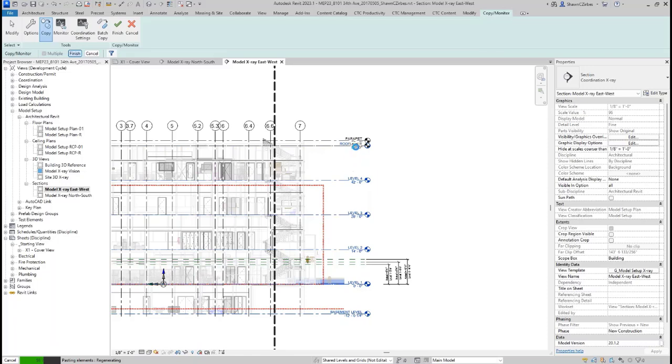The wheel will stop spinning for one, but my level R here is actually going to get renamed to roof level. So it should update that here in just a moment when it's all done. My level 1, which is capital L, lowercase evil, will become all caps as well, and it'll be called level 1. Because of how I name my views, by the way, it doesn't matter what the actual level name is because I use an abbreviation on my levels so that they always sort the same way, regardless of what naming convention the architecture team tries to use.